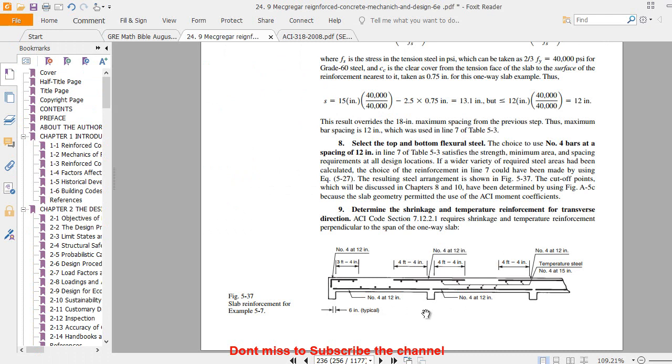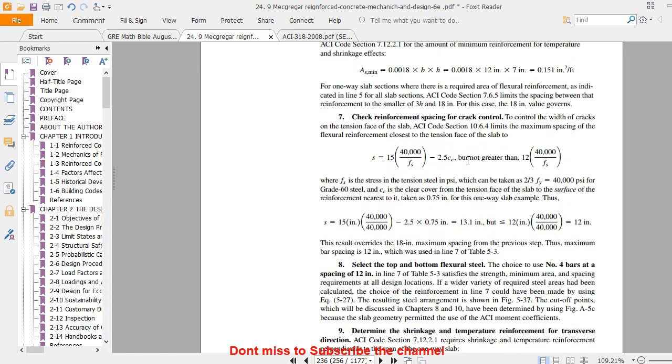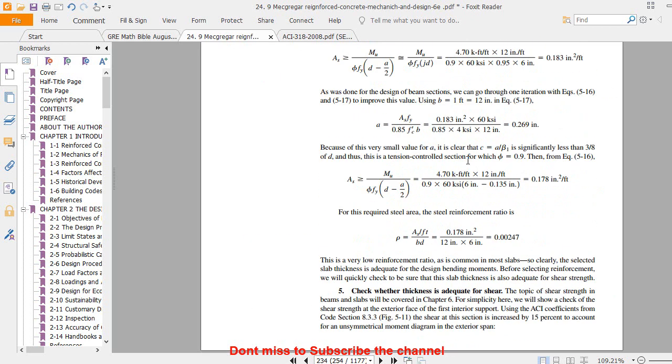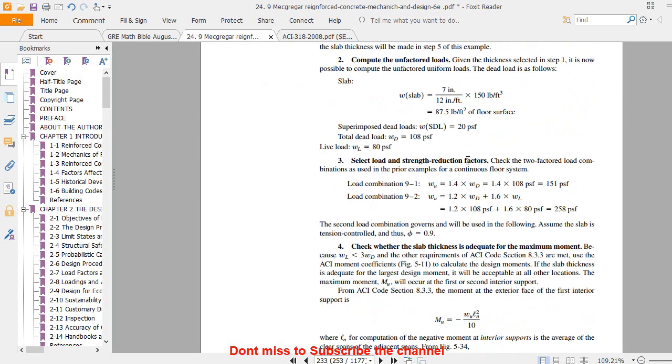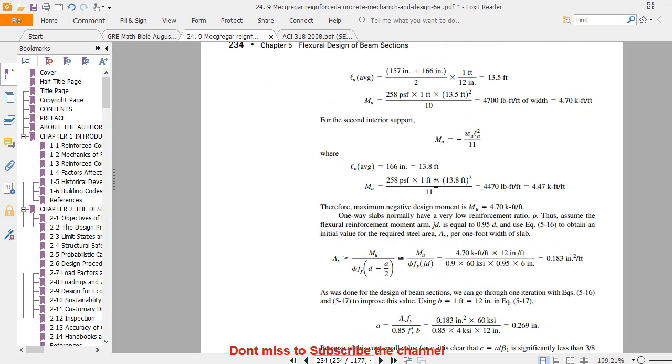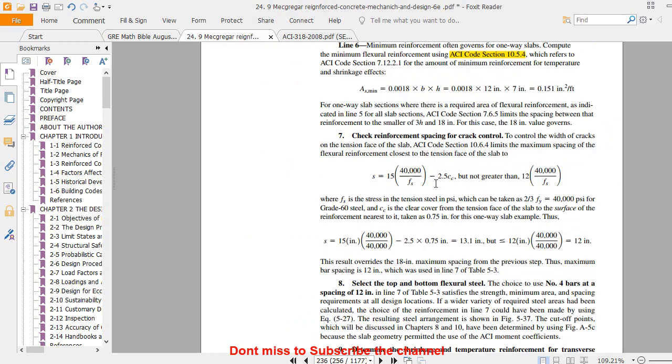And you see here these extra bars which are provided. The effective depth will be minimum, because here you see total 7 minus the clear cover minus the bar diameter and minus half the lower bar. And I think the procedure is simple. I already uploaded so many videos which are just the same as this example, so that is why I'm not explaining all the things.